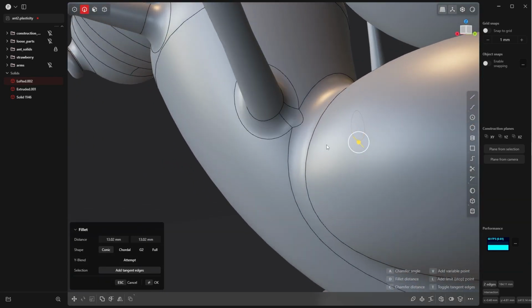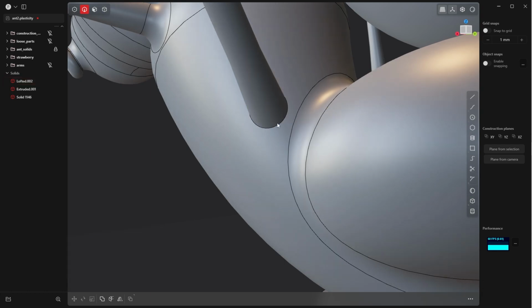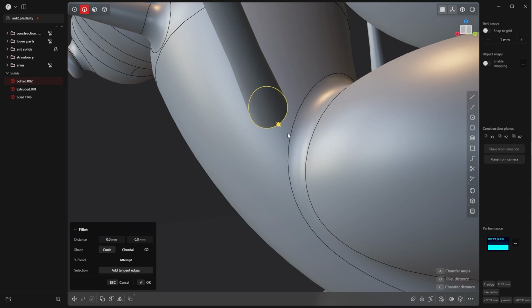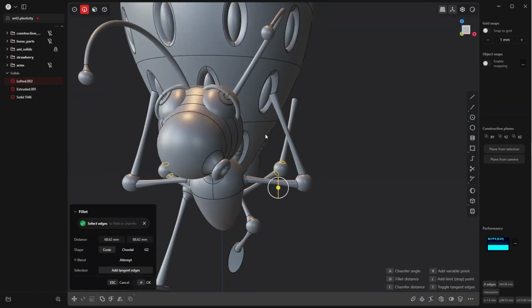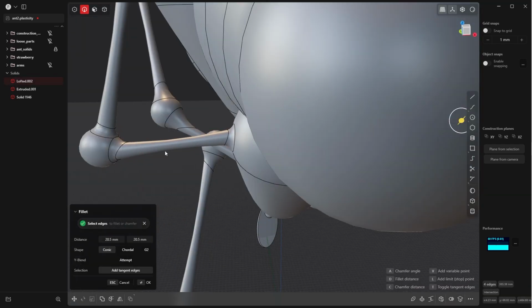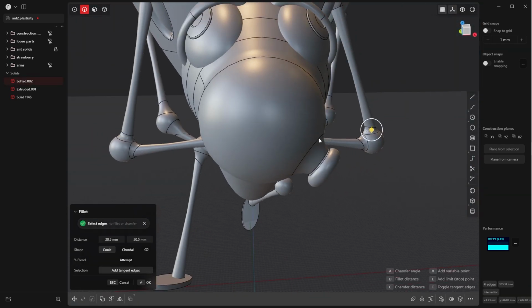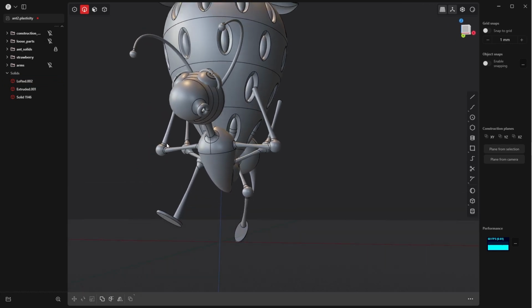Here you can see that we have to make this fillet smaller, or in this case, we can fillet them separately. Here we get a small intersection. We can leave it like this. Like I said, it's not the end of the world. Can also make it slightly smaller. So, I mean, the filleting, I'm talking about this point. Okay, now I guess we have all the fillets.